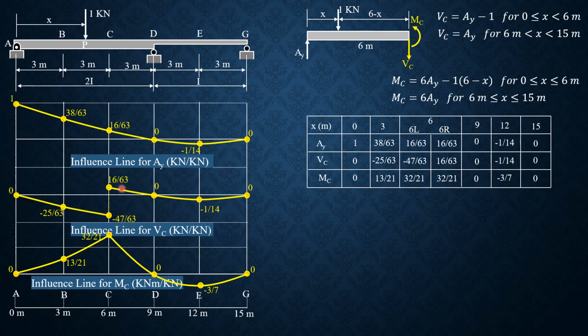So you can have the shortcut by the qualitative influence line technique by Muller-Breslau. So we replace this by a roller which can resist moment but cannot resist shear. So if we push this downward, it will look like this graph. Then just to the right, we push it upward, it will look like that. So that's why it looks like this graph here, just to verify.